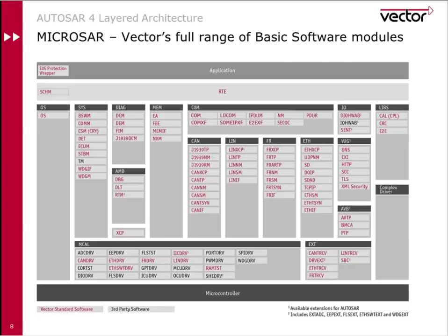Next along, we have the communication modules. And starting here with CAN, we have things that may be familiar from Vector's CAN-embedded days. Functions like CAN network management, CAN interface layer, CAN state manager, and also XCP on CAN. Then we have communication stacks for LIN, so a similar configuration for the LIN stack, and also FlexRay communications and Ethernet communications for automotive Ethernet.